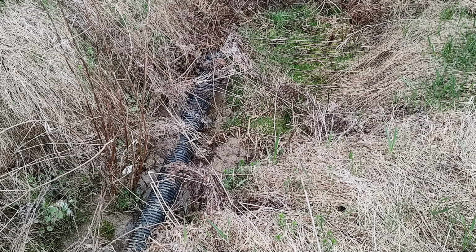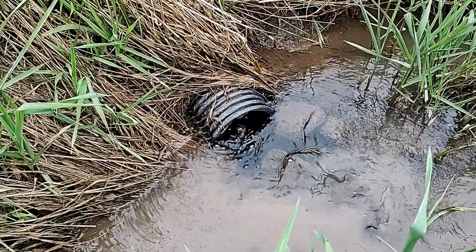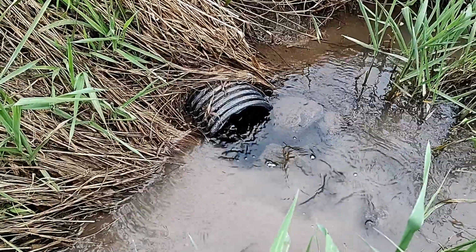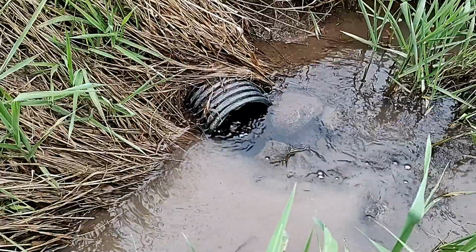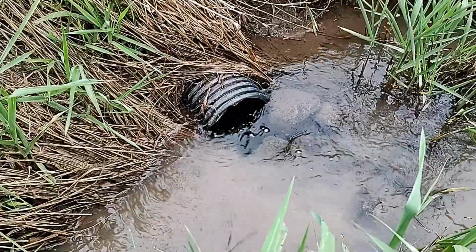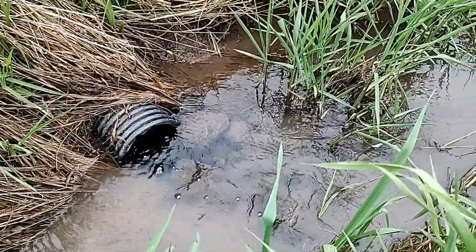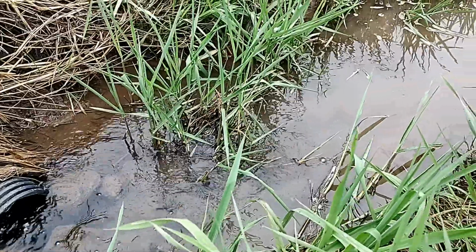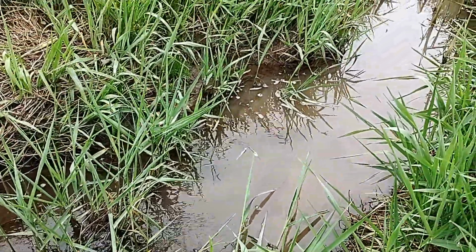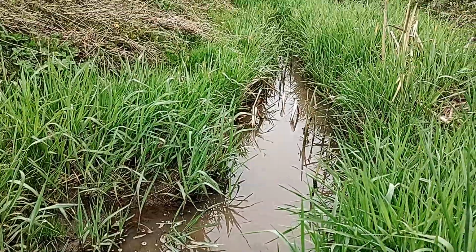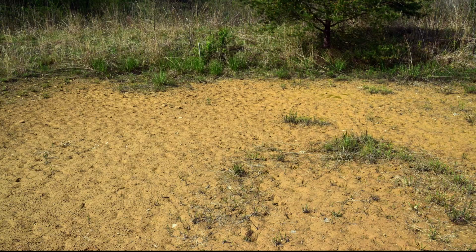Many wetlands and ponds fail to hold water because buried drainage structures were not removed or blocked during construction. Expect to find buried drainage structures in every wetland restoration project you complete. It's of critical importance that you dig a core trench and build a groundwater dam around the lower 2/3 perimeter of each wetland you build, this being done to disable buried drainage structures and to block subsurface permeable layers of soil. This wetland is dry because the texture of soil in the dam and the basin is too low in clay to hold water.